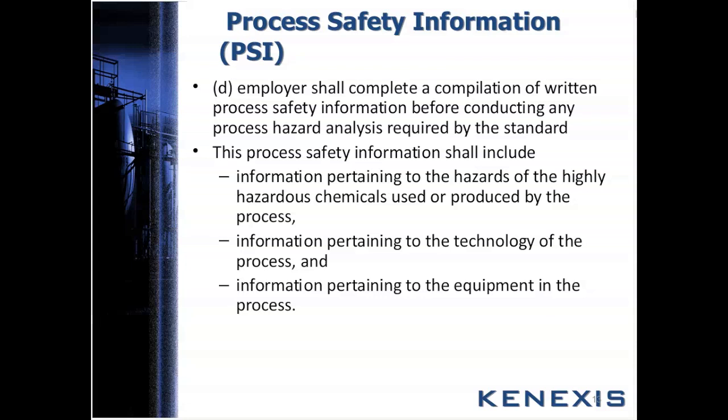A good practice for a HAZOP or any PHA, if they've got specific chemicals, not necessarily hydrocarbons, although you can review those, but I'm talking about specialty chemicals in particular: go over the hazardous chemical MSDS with the entire PHA team before you start so that they can understand the kind of issues we'll be addressing, the reactivity, chemical stability, flash point, things of that nature.